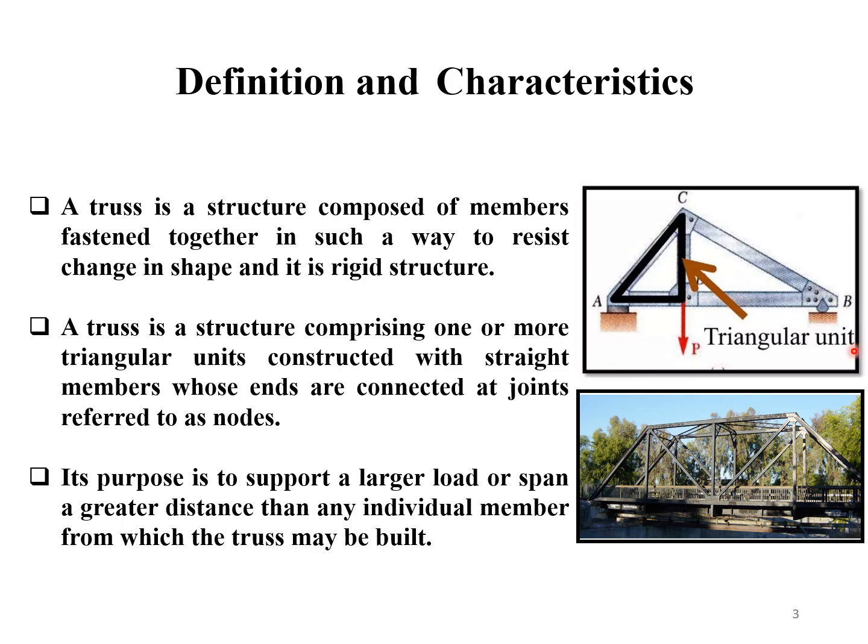If a load is applied, the angles of the triangle won't be able to change if the length of each of the members stays the same. This means that the triangle is a very stable shape which won't deform when loads are applied to it. And so it's a great base from which to build a larger structure.